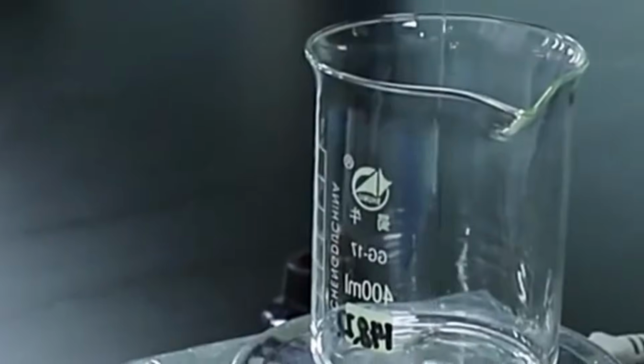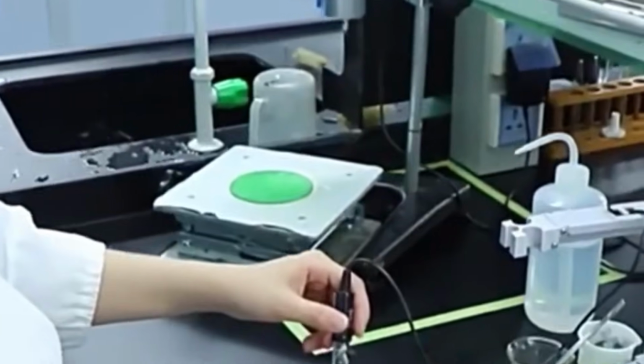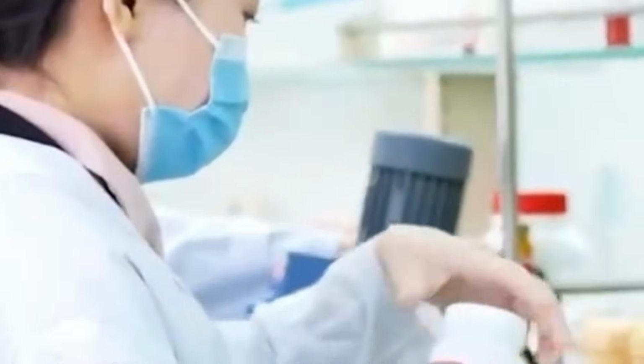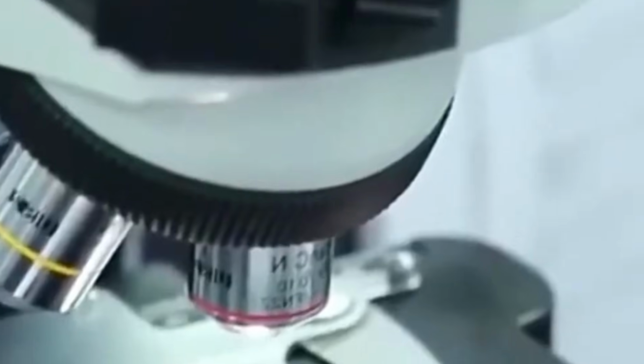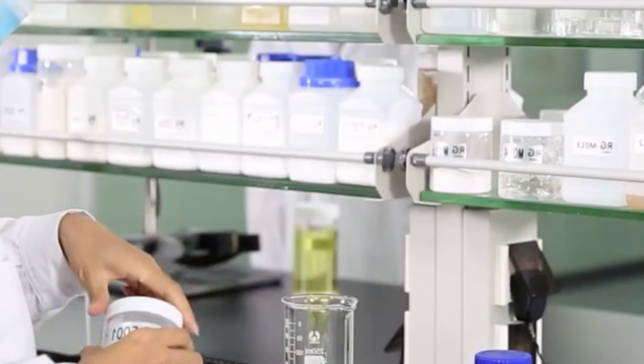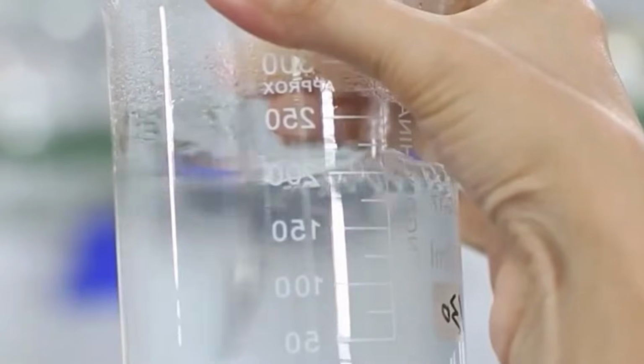Bottles are then grouped for secondary packaging. Automatic packers collate bottles into predefined counts and load them into cartons or trays. Cartons are erected from flat blanks and sealed using hot melt adhesive. Case packers arrange cartons into shipping cases according to palletization requirements.